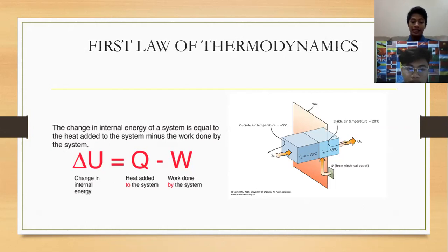QH represents the thermal energy transferred to the inside of the house. W represents the work needed to achieve this. TC is the temperature of the heat pump's working fluid, and TH is the final temperature of the heat pump's working fluid in vapor mode, and TC before this in liquid mode.